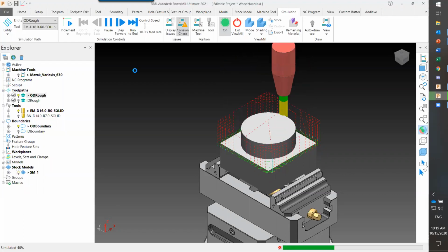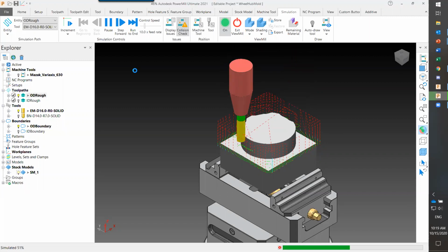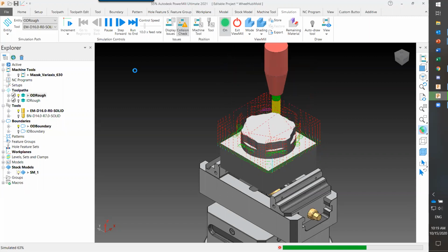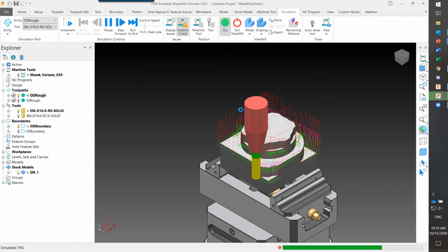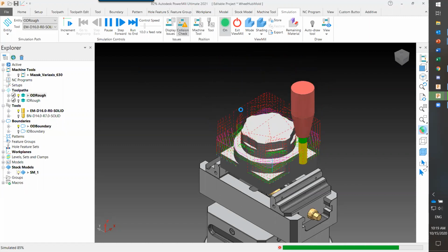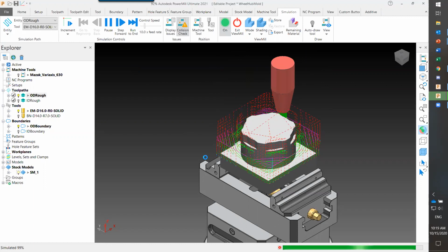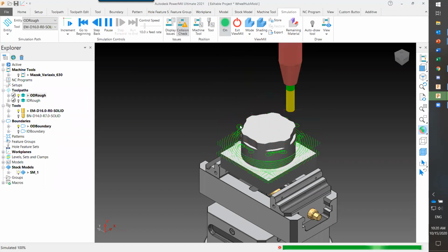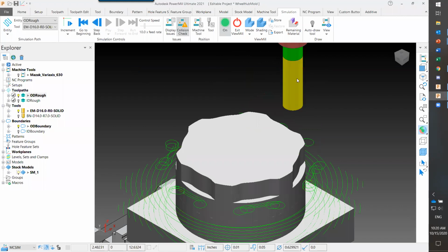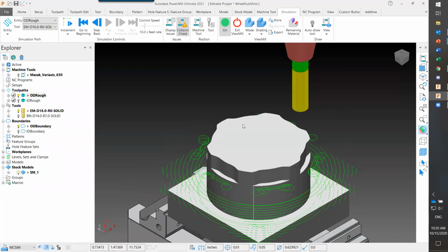So very traditional toolpath. If you guys are coming from Fusion, or maybe from a different CAM software, actually, what I'm using here is called vortex milling. It's called adaptive in Fusion. It's probably called hypermill in some other softwares. Again, the benefit of vortex milling is that you're controlling the optimal load of the tool, so you can machine with a larger part of the flute length, instead of doing that traditional style toolpath where you're only machining with the bottom 50 thousandths, 60 thousandths, or even 100 thousandths of the tool. So now you can engage the entire material with more of the flutes here.